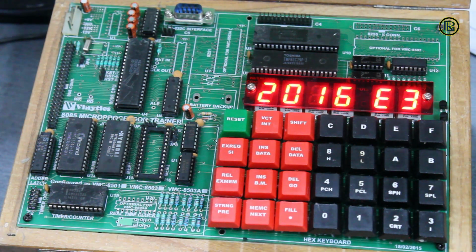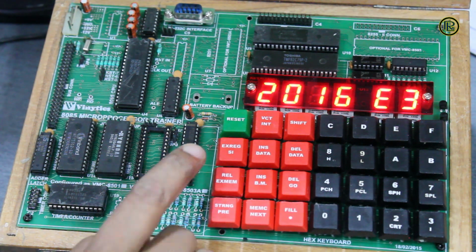First let me show you how to get the addition of numbers using direct addressing mode. As I showed you in the slide, we first have to select two numbers and store them in two different memory locations. I am choosing two numbers, 3A and 8F, for my problem. 3A is stored in the memory location 2050, so I have to store that first.